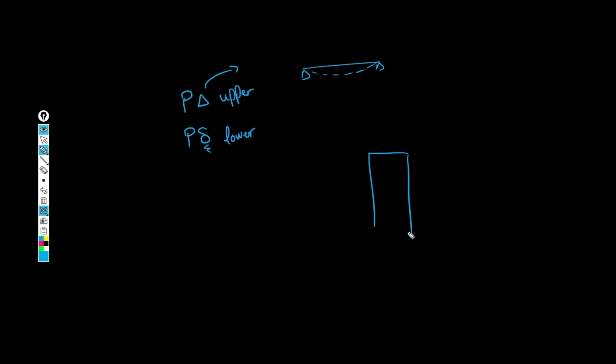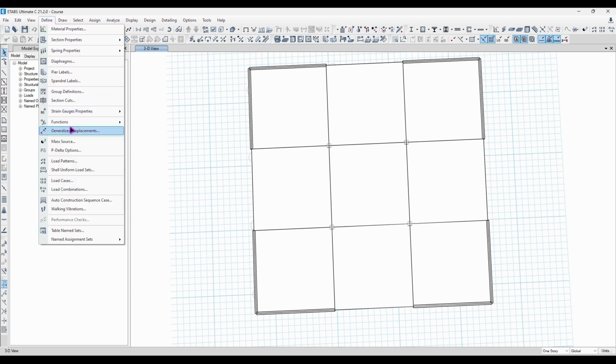Also, notice the difference between the notation of the P Delta and P delta. So one is uppercase, and one is lowercase. In the uppercase, we're talking about the deflection that happens because of creep or just long-term deflection. However, the lowercase delta is when you have a high-rise building, right? And it's affected by some kind of wind load, like this. What happens is the building drifts slightly away from where it was initially. So by applying the load on top, or by applying its own weight, there is a little distance, which is called delta. So this is another effect of P delta. They both have the same effect because it's a distance multiplied by the axial force acting on it, but they just have two different notations. You can go back to define again, as we said, that was the P delta in a nutshell.